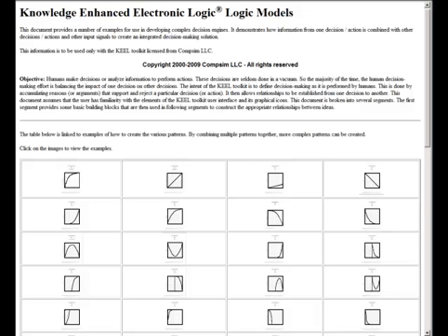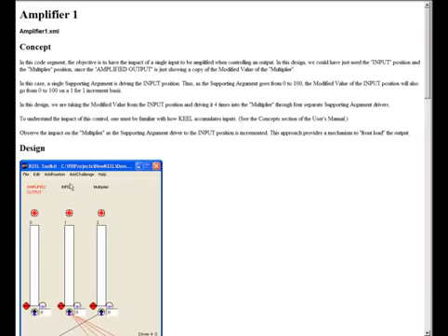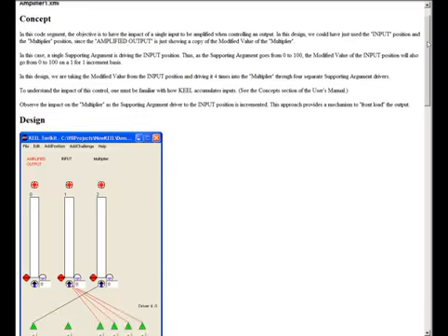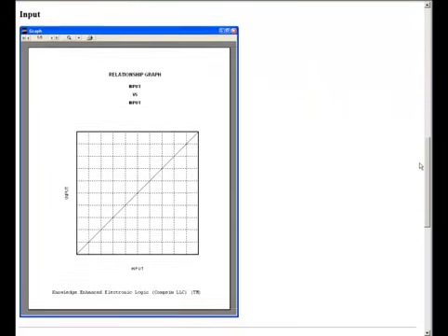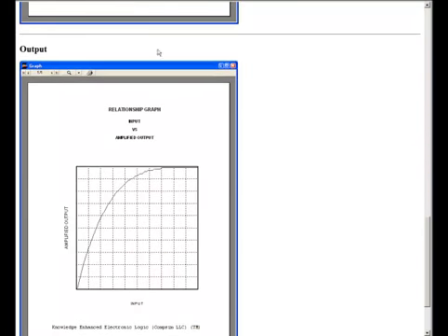You can also merge in multiple curves and splice them together quickly to make very complex curves, such as EKG curves in the medical world. Left-click on one of the curves. You'll see the name of the curve displayed at the top of the resulting page and the XML file name just below it. That's the file that you would merge into your design if you selected that particular curve. If you scroll down the page, you'll see the KEEL design for that curve, and if you continue scrolling down, you will see that curve.